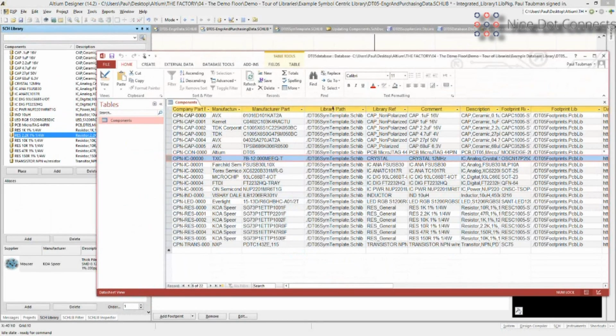Now, some people will argue that you don't need to have this library path or this footprint path in your database, because there are switches that you can turn on in what's called the .DbLib file, and I'll talk about that in a moment. I don't like doing that because in my support days, when people turned those things on, Altium would find whatever local library was close to this database, and many times people would build a library, but they would have another library hanging around. If you check the box saying, hey, use the libraries that are hanging around the database, it would always find some other library, and as a result, we'd get these calls, and we'd have to go fish through all of their stuff to try to figure out where the first instance of their symbol was coming from so that they could correct it.